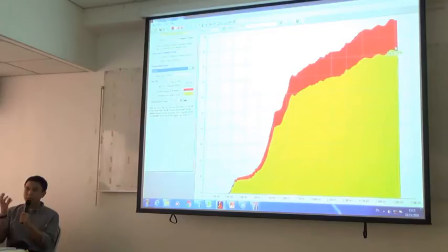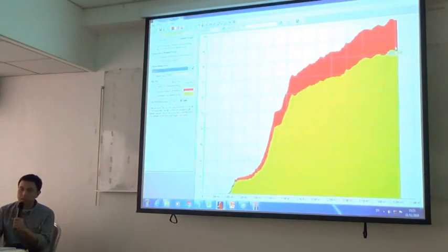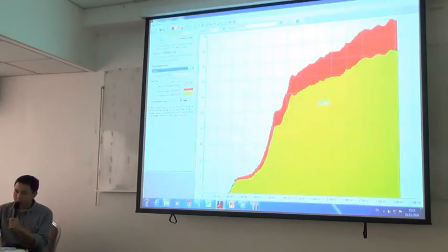So from these graphs, we can qualitatively assess whether the members are yielding or not, before we check into detailed rotations. Based on these plots, we can determine whether the shear walls are yielding or not without checking the strain values.